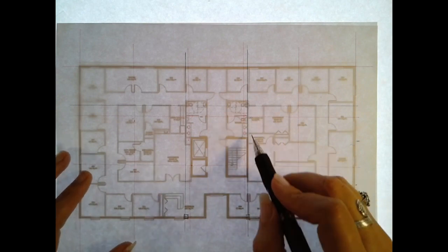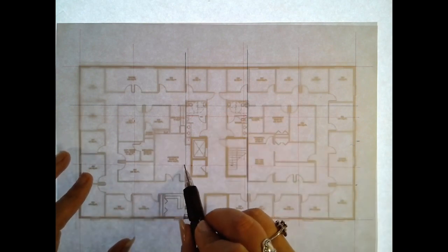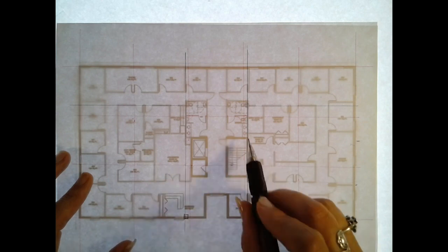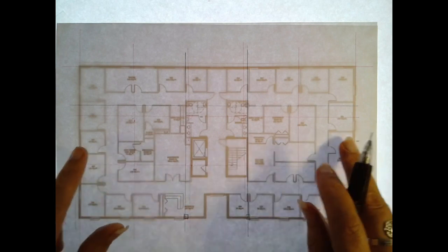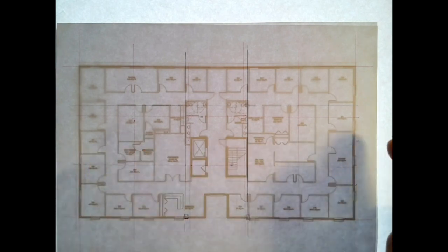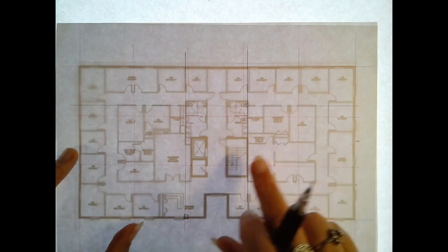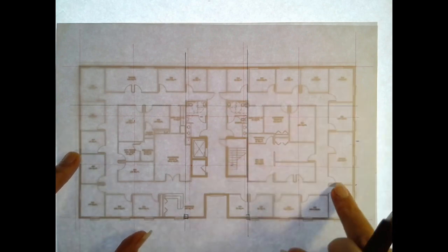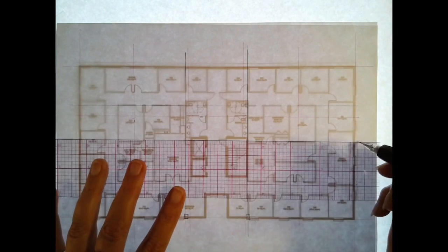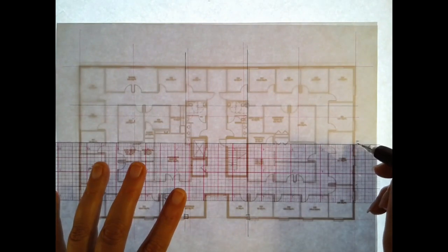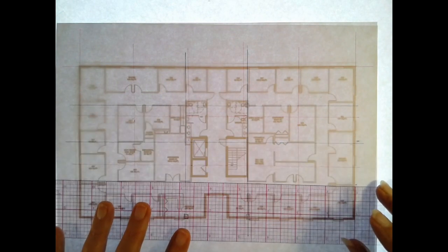So it really is a back and forth kind of play between architecture and structure. You have to say, well, is that okay or not? And how are things lining up? I did several experiments here and came to the conclusion that for this one, without making more changes architecturally, I want to split this up into something closer to fourths instead of thirds. And so that gives me another column line right along here, and then one more